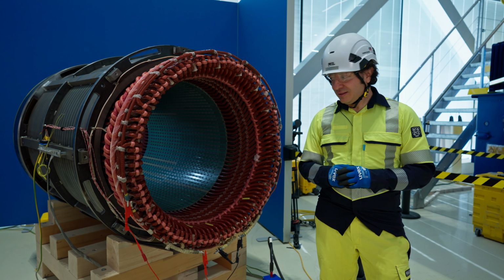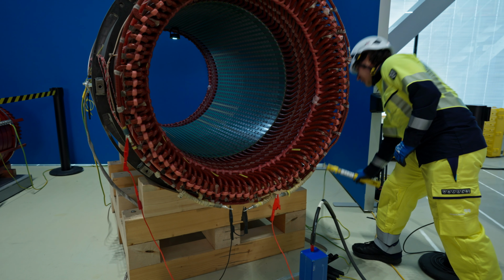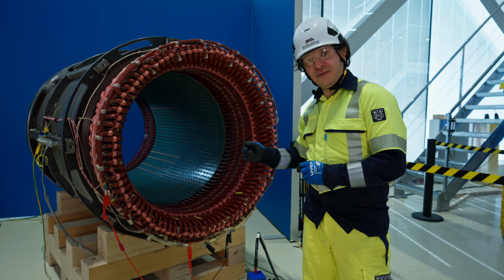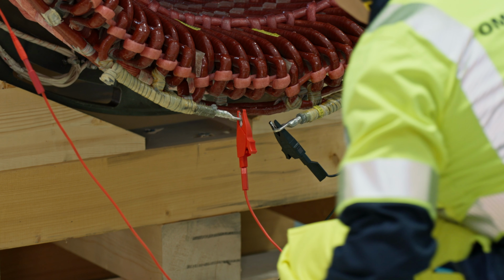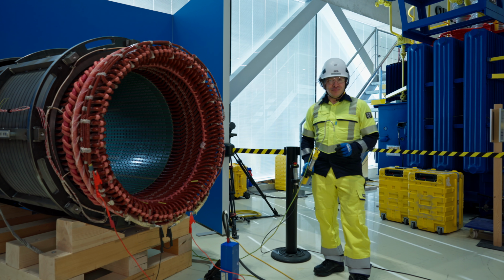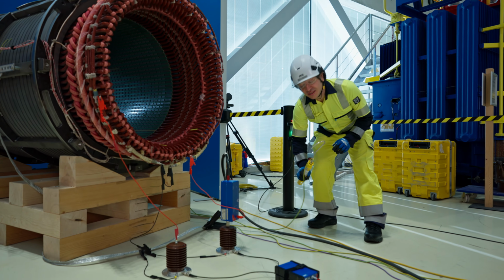This stator winding is a three-phase stator with the start point accessible, so that's why we are going to measure phase by phase. While we are testing one phase, the other two phases will remain grounded. Safety is always very important before touching any cable or any connection. Make sure that it is completely grounded.